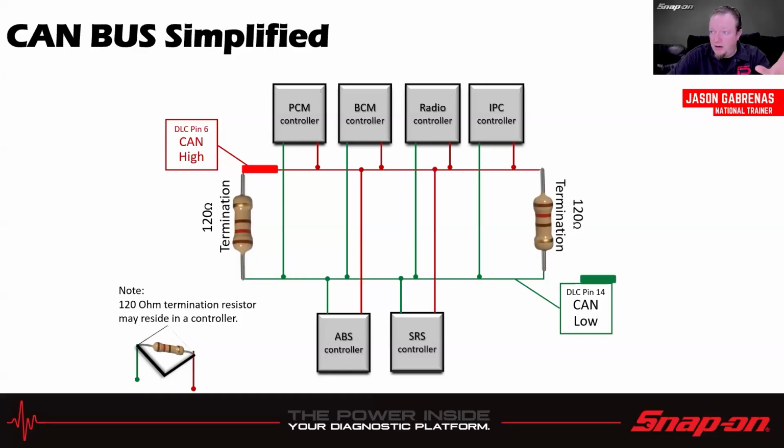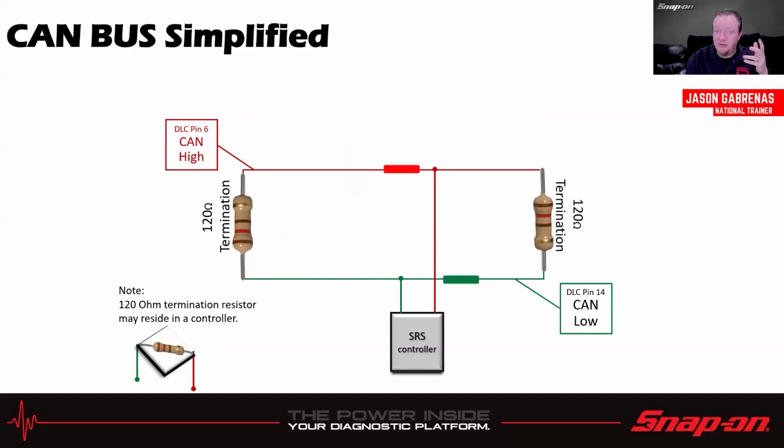So they decided to move out and branch off into multiple buses. There are a couple of different ways they could do it. They could either terminate the buses at the OBD2 port, or they can have it go through a gateway module, which would separate it out. And we'll talk about gateway modules here in a little bit. Or other ways that we might see a little bit later, like breakout blocks and termination blocks. And also, we can remove all the modules but one, and then one module will talk.